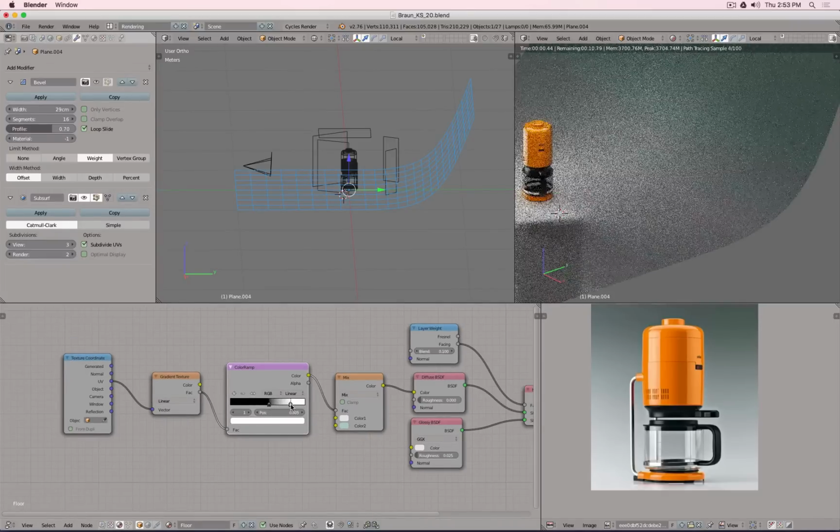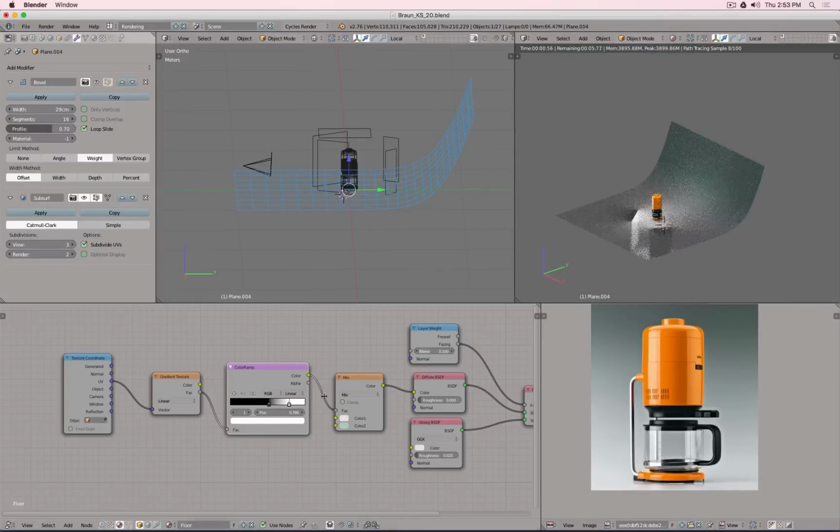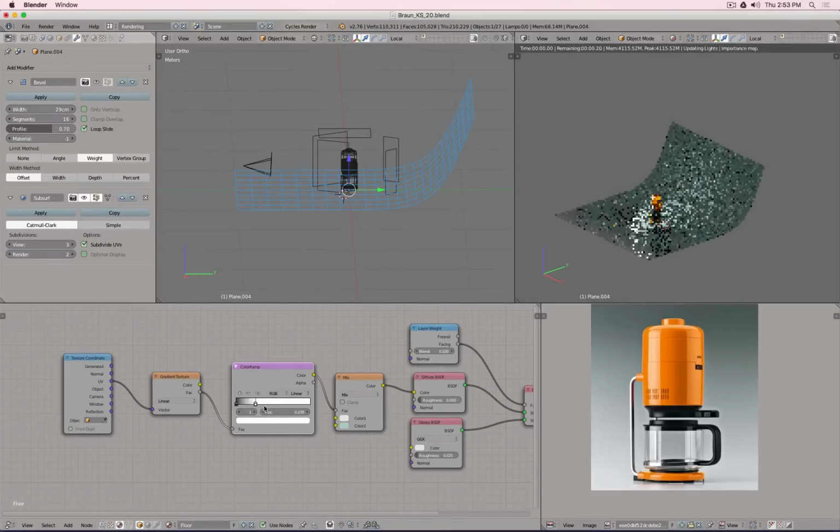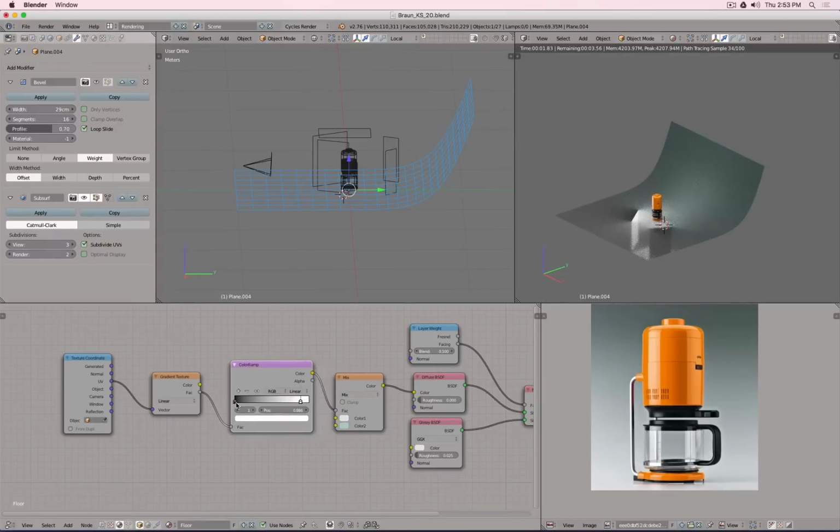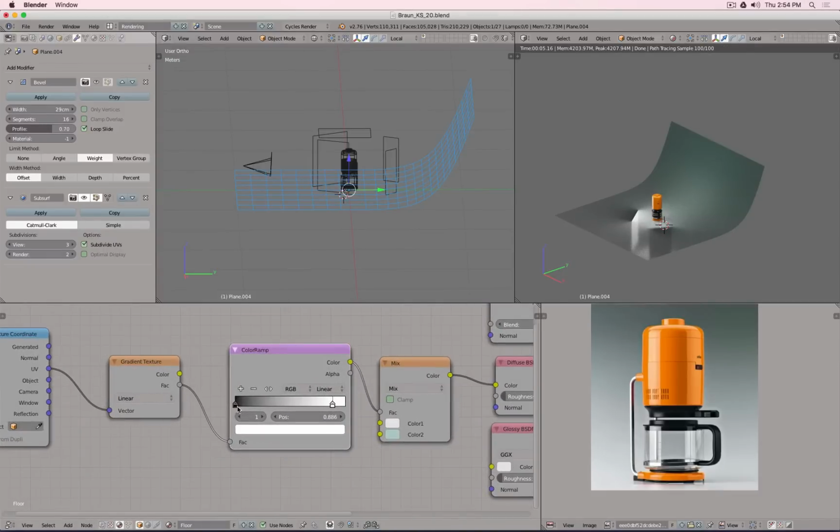And then with this, I can, for example, soften this up a little bit more. So you see we have a lot of the white material. And then actually it blends into this bluish material. So black and white are like markers on the surface. If, for example, I move everything to there and the white to there, so I go to the left side, which means in this case the front, you see the majority is bluish, only a tiny part is white. So this way you can easily override how the blend function works and where the colors are mixing.